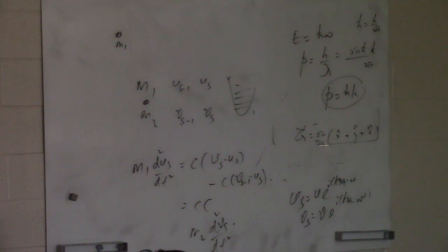This is a very important phenomenon. That's how people try to tailor the thermal properties of materials. If somebody wants to reduce your thermal conductivity, what you have to do is introduce more phonon scatterers. If a phonon is moving like this, if they can get scattered, the thermal conductivity becomes less, right? Where can they get scattered?